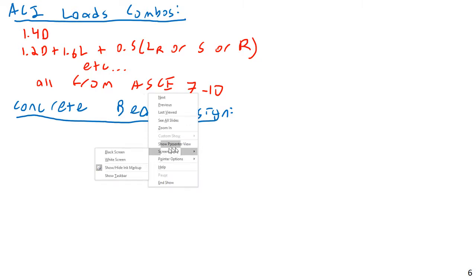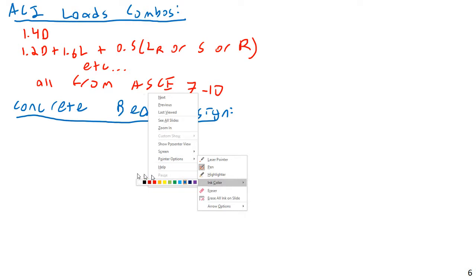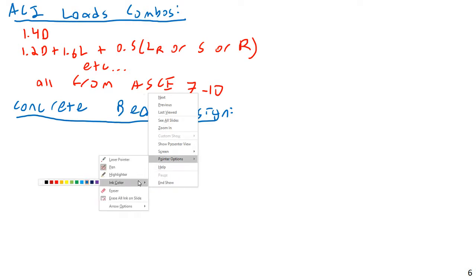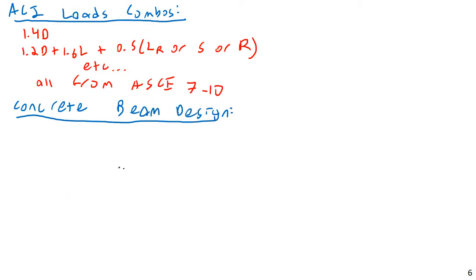If you have a simply supported concrete beam, it's going to need to be designed for a whole bunch of loads, all of them simultaneously, but to different levels depending on load combinations.